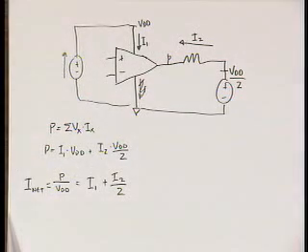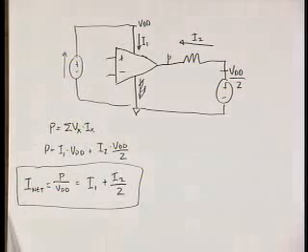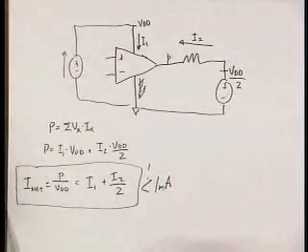Everyone see that? So this is actually how we define the current consumption that needs to be kept under 1 milliamp. This must be less than 1 milliamp. And this has to be less than 1 milliamp, I believe, under the entire range of VDD and Vout. Okay?